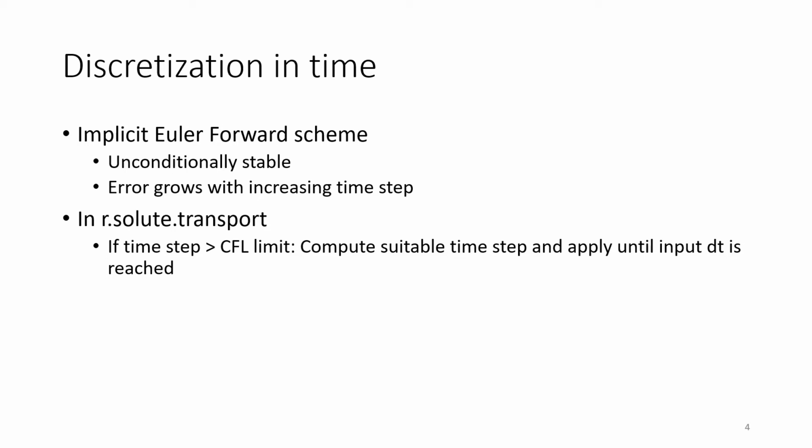So it's still implicit, but if you provide a time step that is larger than the time step that is suggested by the Courant-Friedrichs-Lewy stability criteria, which you hopefully already also remember from last time, then it will automatically compute a suitable time step which fulfills the CFL criteria.